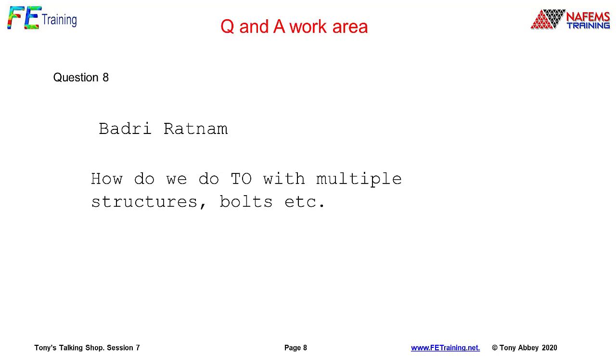But what's interesting there, the individual ribs, you might say, well, I can bound the load path through these ribs, so I could use topology optimization to design the ribs. So do I come up with a plate type rib, or do I come up with a Warren girder type rib? That distinction and that local detail could be done with, say, topology optimization. There is a danger there because you can show quite easily that optimizing parts and then bringing those optimized parts together isn't necessarily an overall optimum solution.